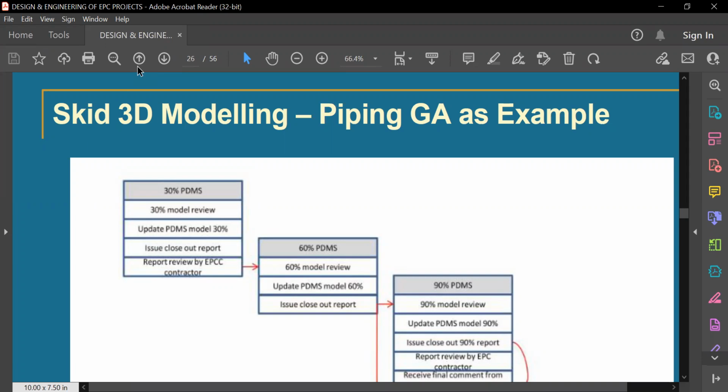In this case, all JBs will be shown, all instruments, the PT, pressure transmitter, where it is coming, and how every cable and every JB is routed. For example, a pump is there, from electrical or mechanical, then the LPBS, local push button station, where it will come. And all these things should not obstruct the people who are working there.